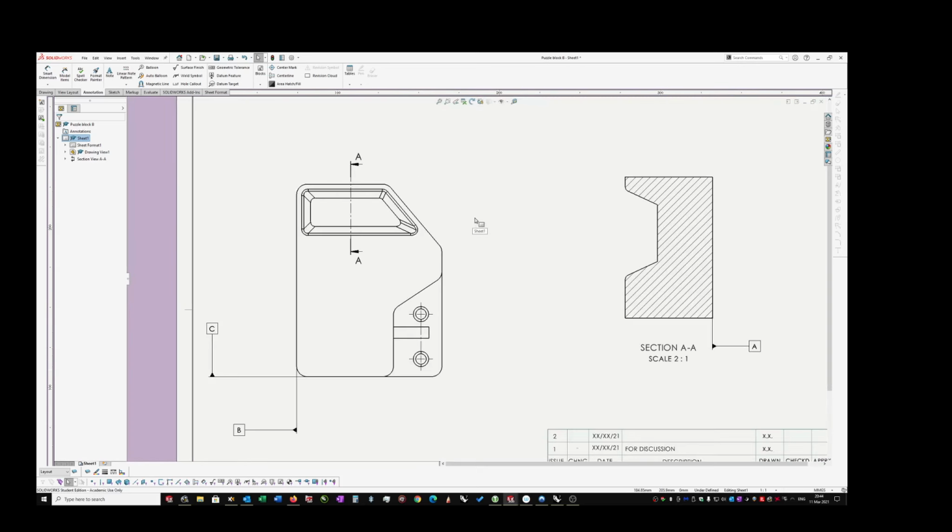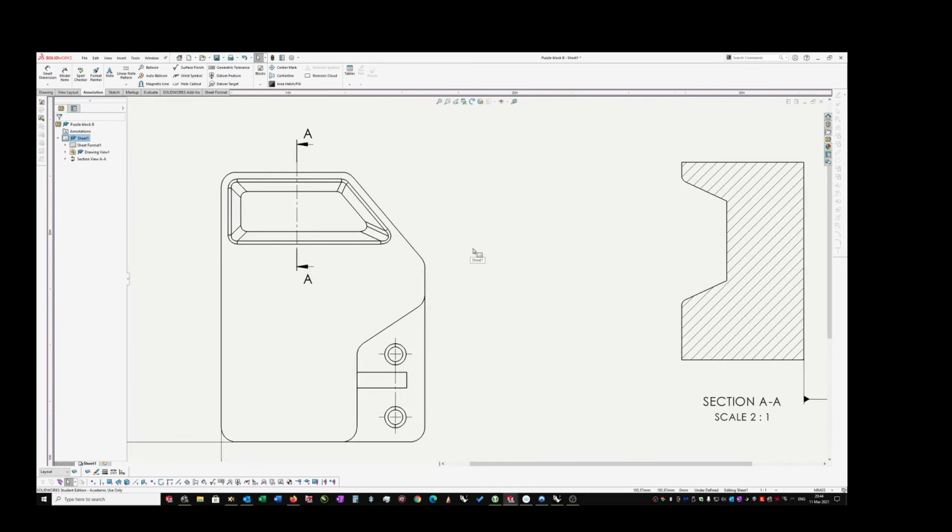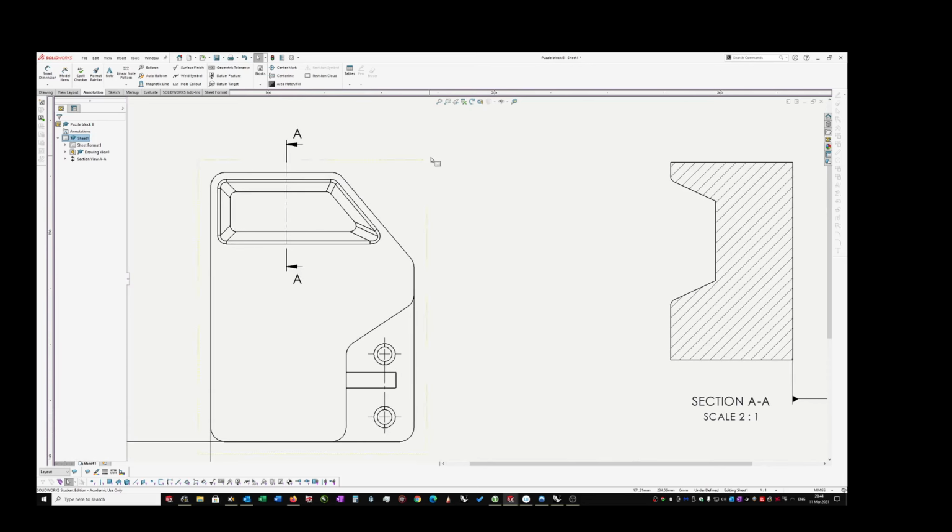Right, the other thing I'm going to need is I want to dimension this angle, and that angle, and that angle, and that angle, and that radius, and that radius. But I've got nothing against which to dimension them because I've got these fillets in the way, and that's why I gave you this drawing full of fillets so that you could try and deal with this problem.